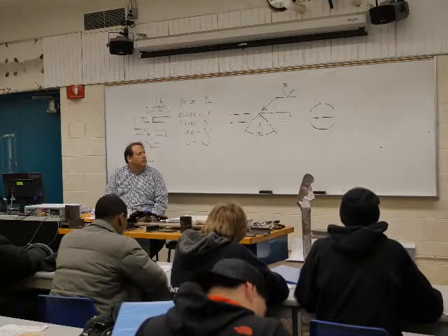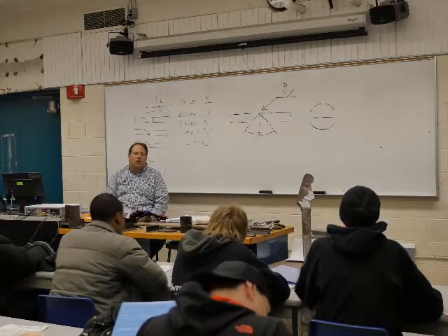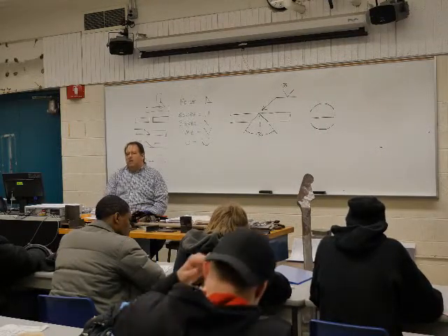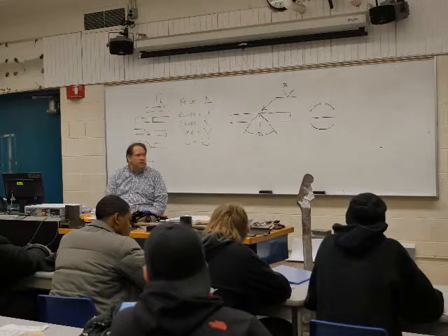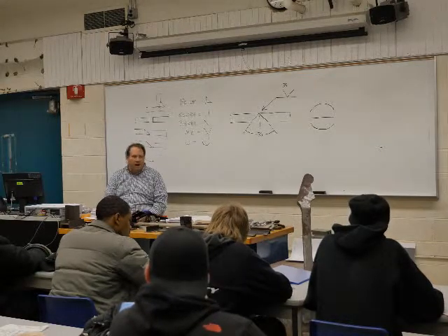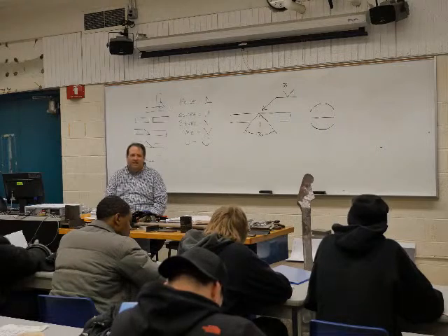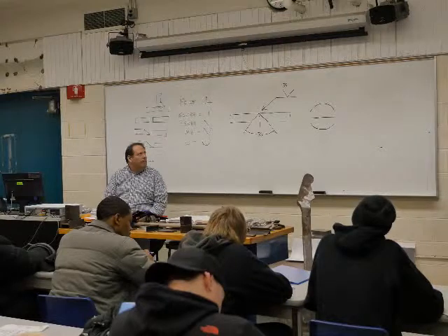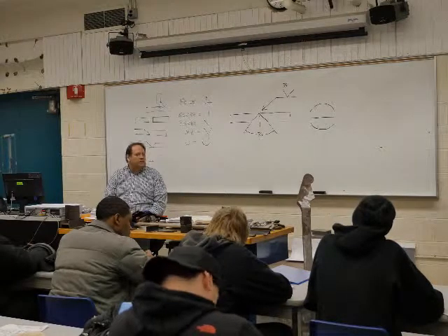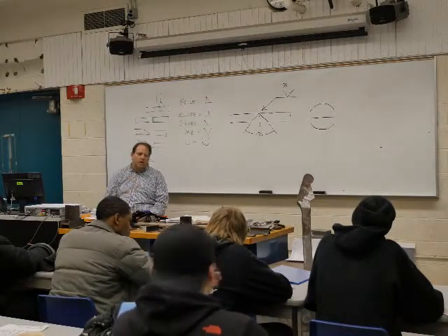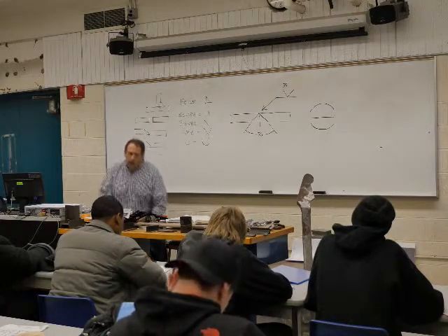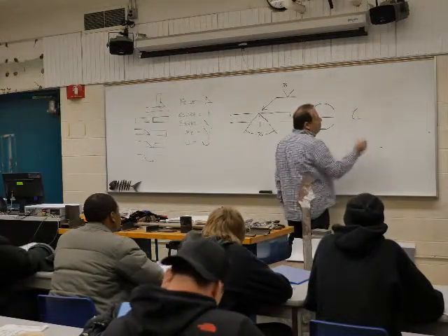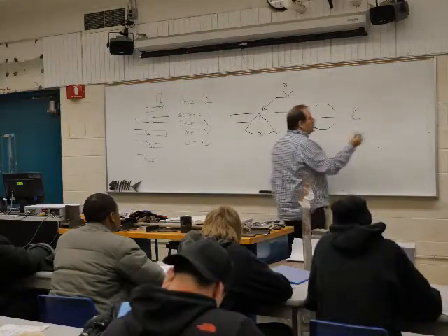So for groove welds, you don't see a whole lot of a contour symbol except for that flat or flush symbol. In the fillet welds, all you're really seeing is either flat or flush or a concave. Convex, not that often. You're not going to see that asked for too often at all. This is going to be dependent on the second part of that, which is the finish symbol. And the finish symbol can be one of 3 letters. There's actually more, but for our book and everything else, these are the only ones we're using.